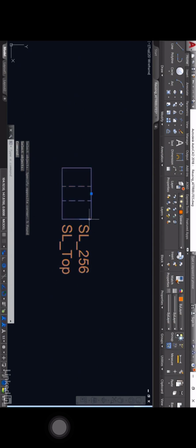If you double click on the block now, you can edit those using the enhanced attribute editor. Because it's a block, you can't edit its physical attributes, but you can edit its block attributes. So you can see there that I can change the sleeve number, I can change the sleeve name. What I can also do is in the text options, I might change the colors or the properties, for example. So I can do that because the color at the moment is by layer.